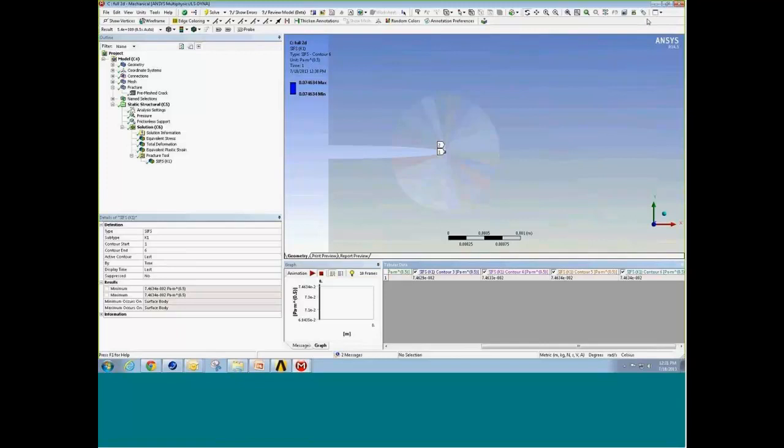That's sort of interesting, but it's only 2D, and we had to come in with our crack geometry. By the way, you could have come in with a crack mesh as well if you built something in APDL, and you could bring it through FE Modeler, you could bring in the whole mesh already with a crack in there in your complex 2D or 3D geometry. You could do that as well. Again, you would just have to add the fracture part, tell it you have a pre-mesh crack, assign the coordinate system and the name selections, and you're good to go.